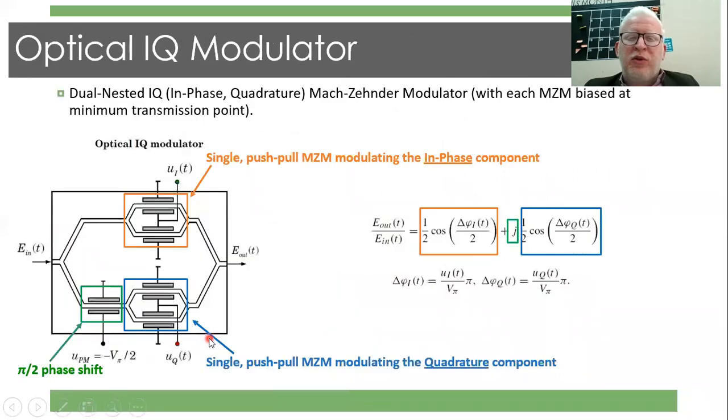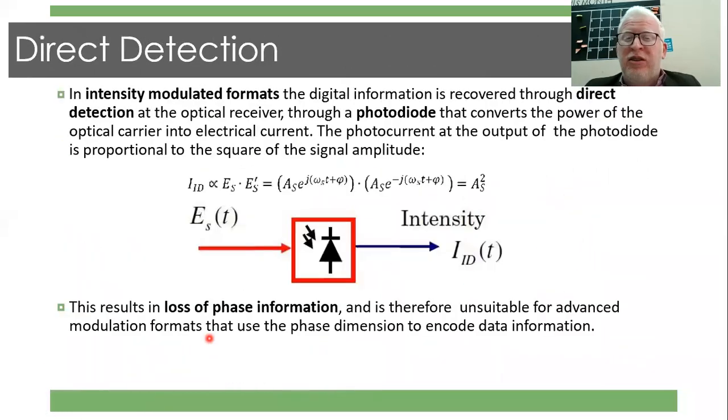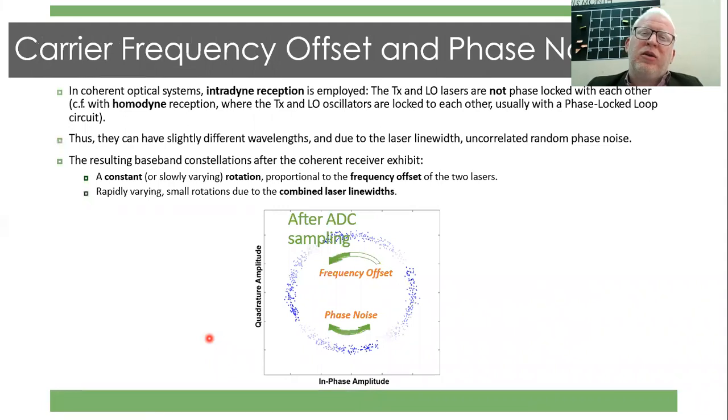Another source of error is the phase error. Whenever you are transmitting with a certain phase, and due to some variation or some losses or some attenuation or even some dispersion in the optical fiber, then you have some phase change, and of course this phase change can introduce error to the system. So these are basically the sources of error for an optical communication system that can affect your demodulation stage with respect to the modulation stage.